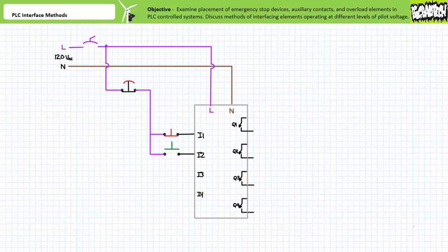If, however, the e-stop is in the activated open condition, the closure of any field input device will not issue a logical 1 to the PLC despite repeated attempts to do so. Wired in this fashion, the hardwired e-stop directly upstream of all field input devices has effectively severed all incoming communication with the outside world without the necessity of resorting to any program to do so. Note as implemented, opening the e-stop would still keep the PLC powered up.